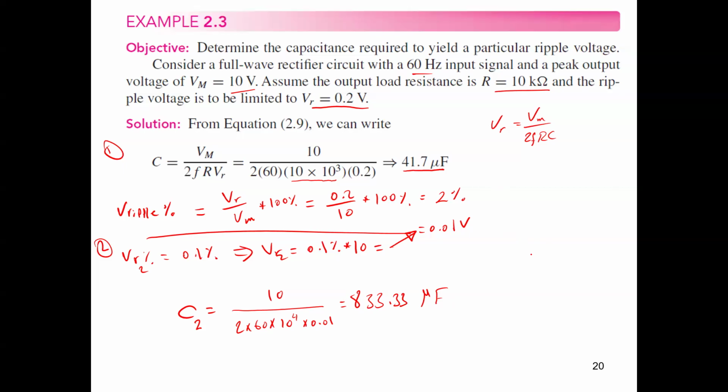If the volt rating is relatively high, guys, let's say a 100 volt capacitor, for instance, this difference may make the price tripled or maybe 4 to 5 times also. So it's going to cost a lot of money to get this high capacitance value. And to be honest with you, it's not that important for the volt tolerance to be just 0.1%. It's not that critical. So 2% is fine, 1% is fine, but 0.1% is relatively high.